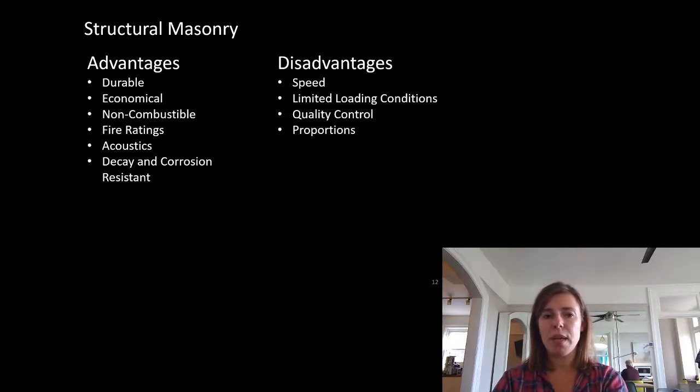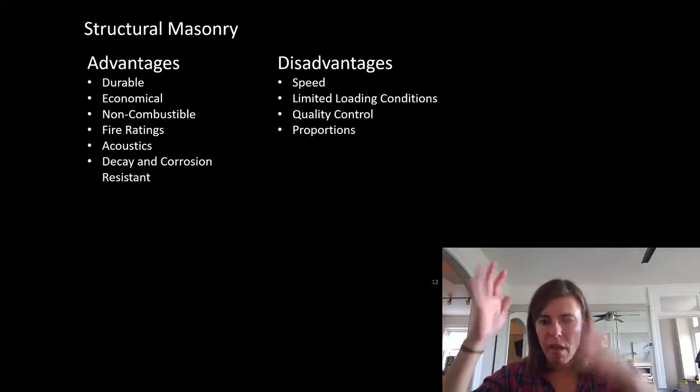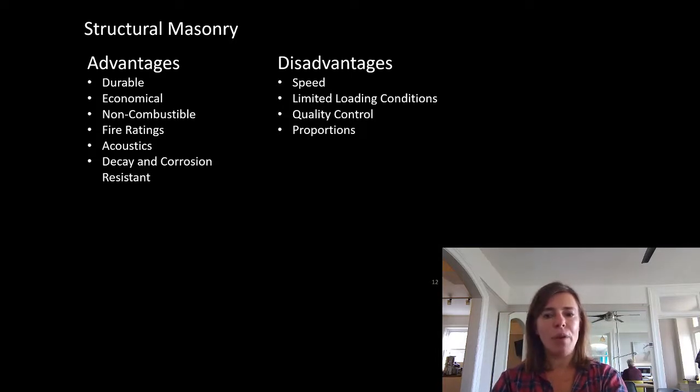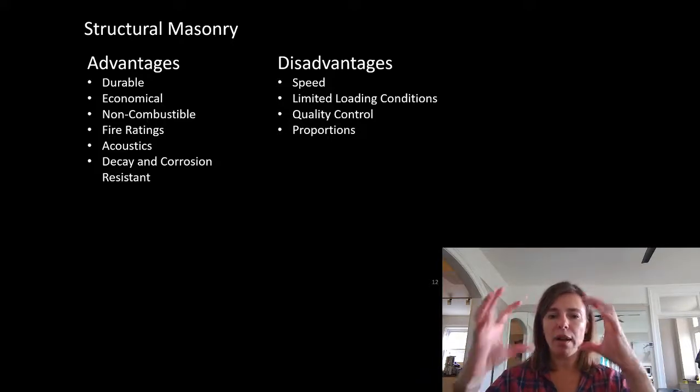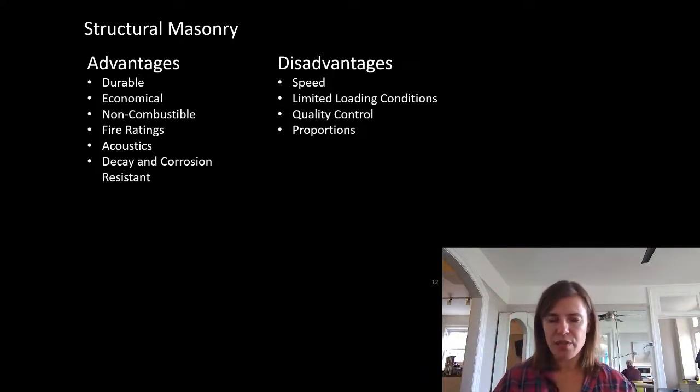So many of those advantages we've already seen in precast and concrete, where really masonry is tiny precast elements that we're stacking together with bits of gooey concrete. We're basically using bits of concrete as glue to hold together all our precast elements. Speed. As much as I said we could knock it up in a few days, we're talking about a 1 or 2 story building. It is actually relatively slow because we take each block and hand place it, do a bunch of stuff to it, place a new one, do a bunch of stuff to it. So it really slows the process down.